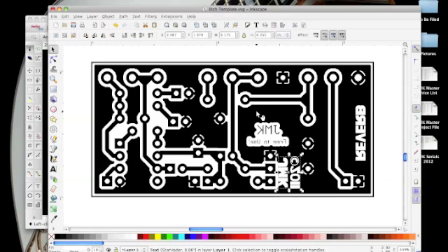What it ends up being is when you etch it, it's like looking in a mirror, right? Everything that you're doing here needs to be mirrored, because when you actually have it come out for yourself, this is the bottom of the PCB, not the top. So it ends up getting flipped around when you actually put it on your piece of copper PCB. So I'm going to remove this because I don't really want it to be in there. But I'll show you how I create it.